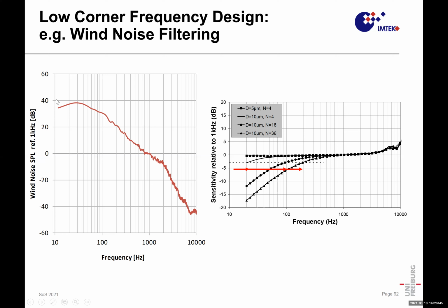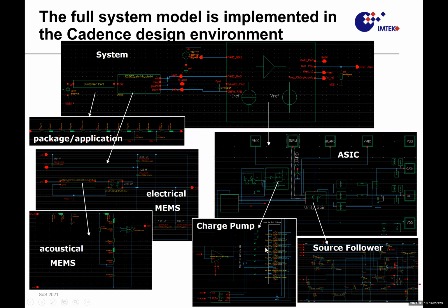And if I look at 100 Hertz, then I have already 10 dB of this portion filtered, and let's say maybe I put it to 200 Hertz, then I am with 40 Hertz, which is this peak here, already 15 dB below the initial pop noise. So I can filter out quite effectively this popping and still be able to transfer voice. And in such a special application, this is for sure beneficial. Yeah, this is such kind of examples.